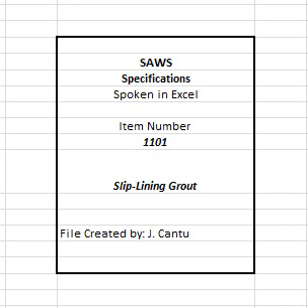3. Equipment. A. Mixers and pumps. 1. The materials shall be mixed in equipment of sufficient size and capacity to provide the desired amount of grout material for each stage in a single operation. 2. The system shall mix the grout to a homogeneous consistency. 3. Deliver grout to the injection point at a steady pressure with a non-pulsating centrifugal or triplex pump at the mix tank. 4. Provide ways to increase or decrease the water-cement ratio and accurately measure grout component quantities, pumping pressures, and volumes pumped.